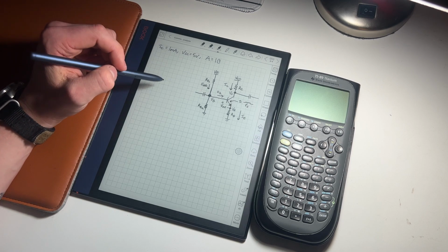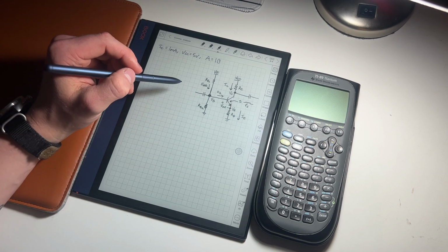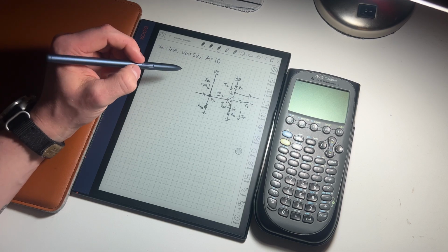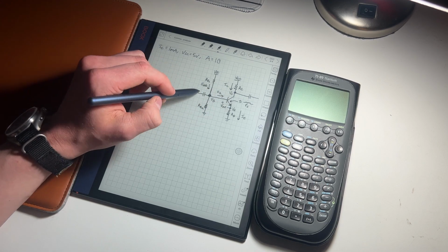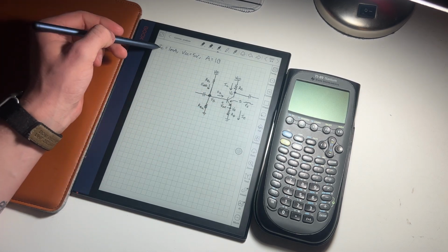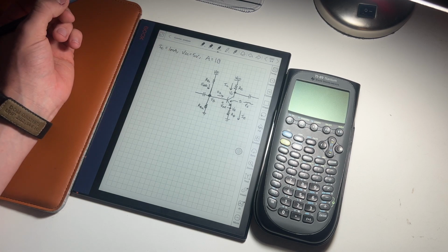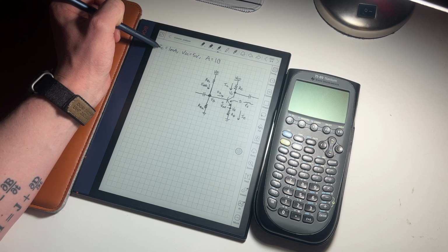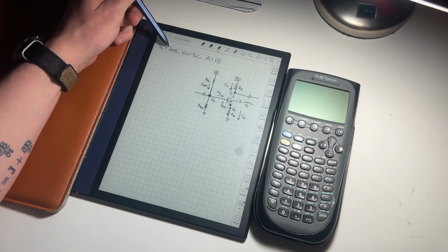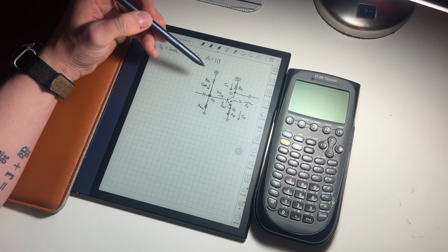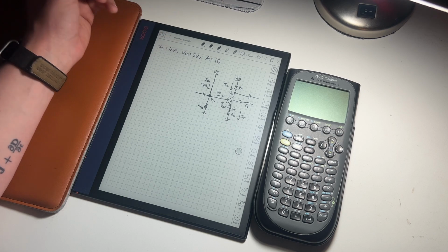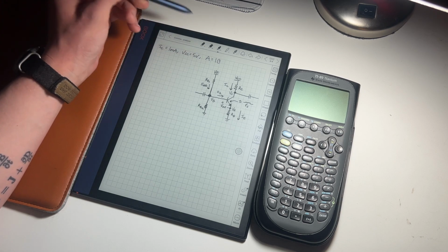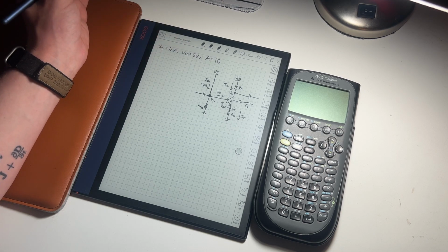So I've done a lot of pointing and explaining, but now we're actually going to work through an example. Here I have the circuit from the last page, and I have some conditions that I've set myself. First, I want the collector current at DC to be around 1 milliamp. I want to run this amplifier off of 5 volts, and I want the voltage gain to be roughly 10.